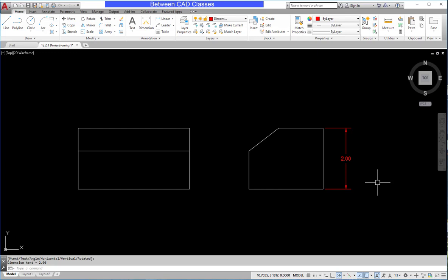the correct thing. I'm going to place a couple of linear dimensions across the top here. I'll start with this first one here, and then I will create a linear dimension on this portion as well. Even though the shape is angled, a linear dimension is going to give me horizontal or vertical dimensions depending on which way I pull my mouse. So I'm going to bring it up and snap to the endpoint of the previous dimension.